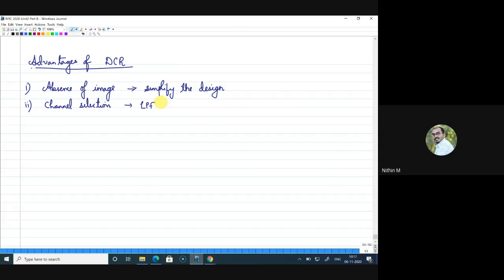And so compared to band select or band pass filters, the realization on chip is comparatively simple for a low pass filter, right? Because even the frequency we are looking at is very low. So on-chip implementation is easy for a low-pass filter, but when it comes to a band-pass filter, we may need to incorporate inductors or other passive components into it, right?